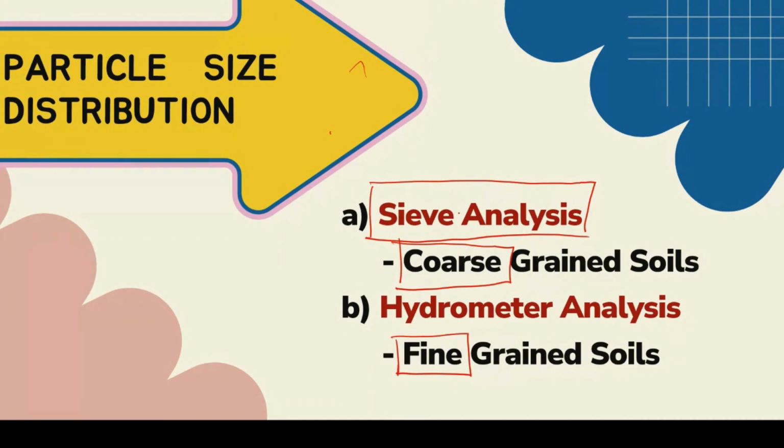When we conduct the sieve analysis, at the end of the meshes, at the lowest tray, we have the pan, which has no mesh, it is just a pan. From that pan, we will proceed to the hydrometer analysis to determine how much silt and how much clay. We will look at it in detail later.